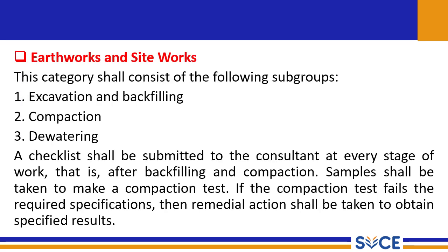Earthwork and site works. The category shall consist of the following subgroups: excavation and backfilling, compaction, dewatering. A checklist shall be submitted to the consultant at every stage of the work, that is, after backfilling and compaction. Samples shall be taken to make a compaction test. If the compaction test fails the required specification, then the remedial action shall be taken to obtain specified results.